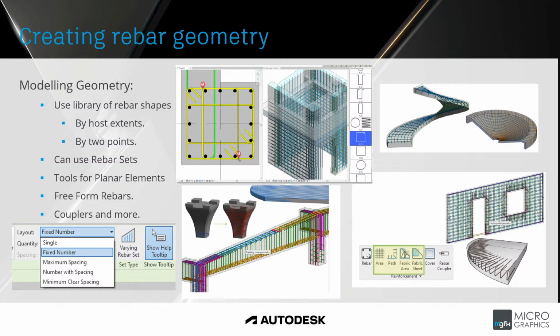So around the openings there is a path, or on the edge of the slab there's a path created with specific shapes that you can assign. Right, now those path based items, if for instance in the wall, those openings adjust, then all the rebar travels with that opening, so you don't have to redo the modeling.